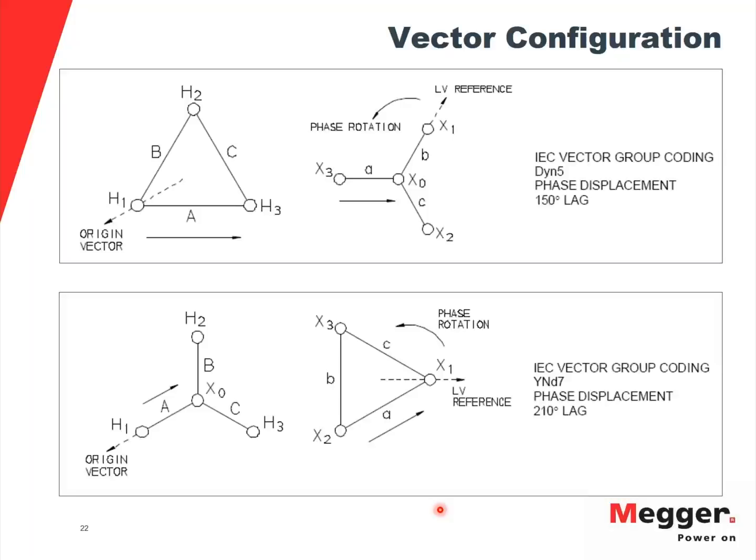Coming back to the question, the 35% of nameplate kVA. As long as your tertiary winding is derated, there is a high probability that you may run into voltage dependency. And if you run into those, refer to the slide that I mentioned, and you will be getting a copy of those. I have seen that anytime there is a derating of the winding, you may run into voltage dependency. But again, as I mentioned earlier, that does not necessarily mean that there is something wrong with the transformer. You just have to use enough voltage to make it work.